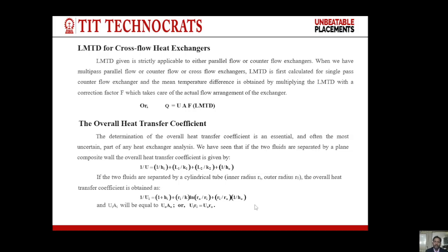Where to use this formula? So we will use this LMTD for calculation of heat transfer rate. In case of a cross flow heat exchanger, we can calculate the heat transfer rate as Q is equal to UAF LMTD.